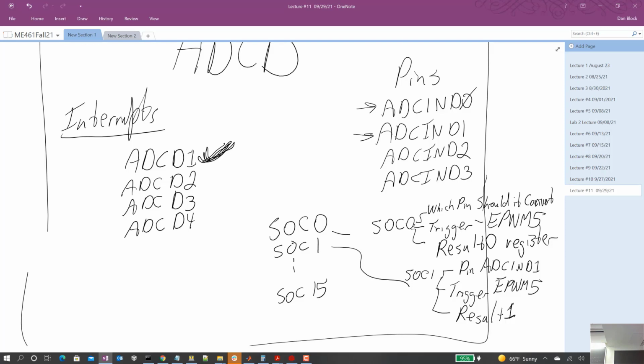When we used PWM2, what did we do? We knew that the clock rate coming into the PWM was 50 megahertz. We set it up in count up mode, and it would count up to the period value, which we set in lab at 2500 to make 20 kilohertz. So it'd count up to 2500 and then go back to 0, wouldn't it?